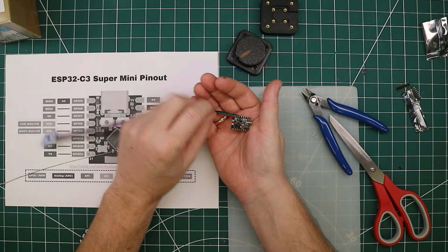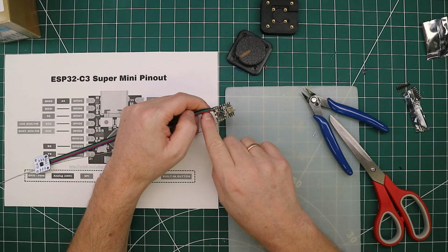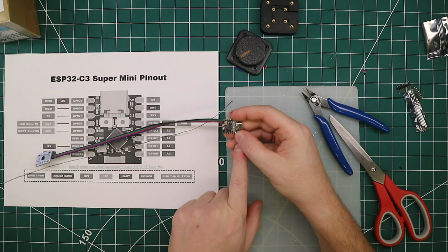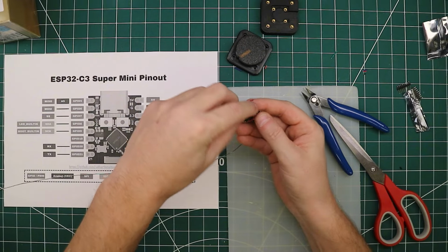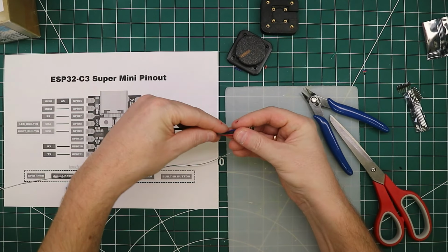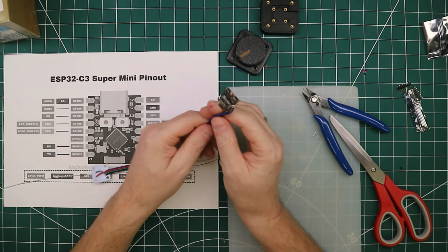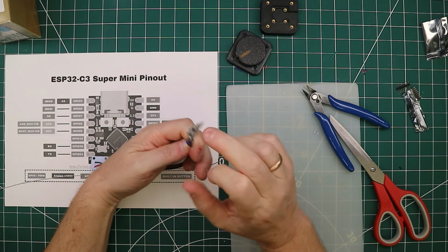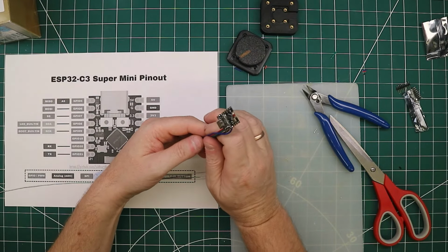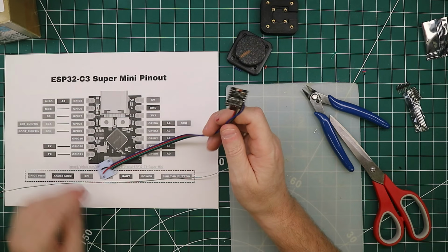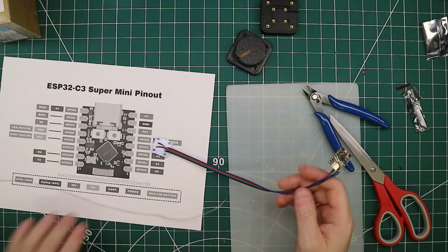Since the antenna on this is really small and not very good, you want to try and avoid having cables going under it. So instead of having the cables going this way, we'll just bend them over and have them go in this direction instead. I can't see that, but now you can. So basically the antenna is going to be free of floating wires around it. That's going to make the reception at least a little bit better. Probably still not brilliant. That should be all the soldering, so we can turn off the iron.